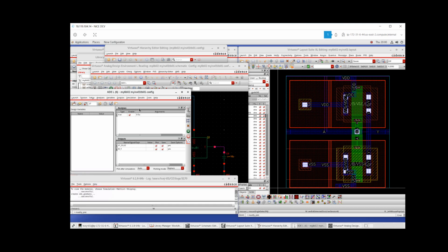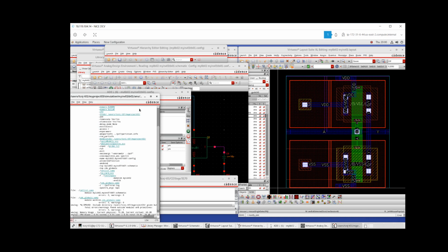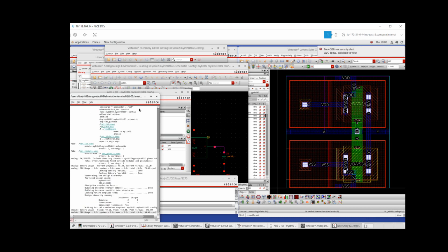We can see a piece of it. So we can see that the input and the outputs are there. And then we can start the simulation with netlist and run. So the simulation is going to start running, and this time is going to be using the post layout extraction. So you can see that the log and the screen, they look a little different as it runs.